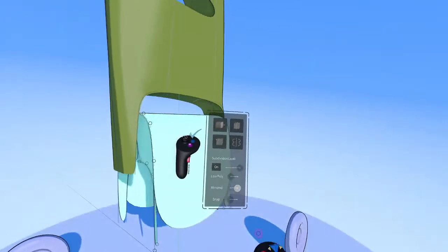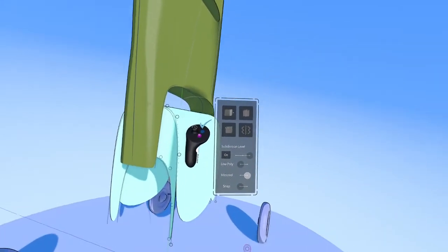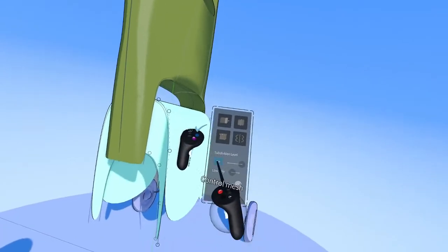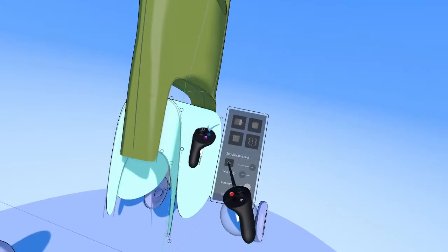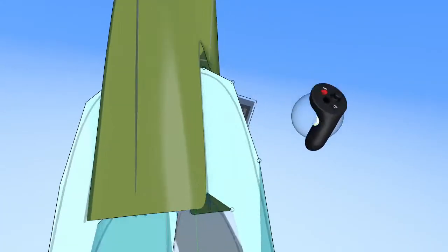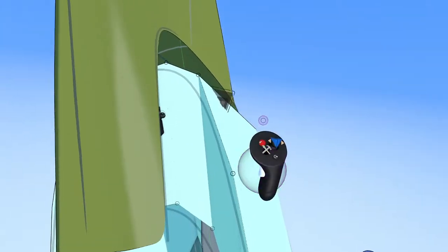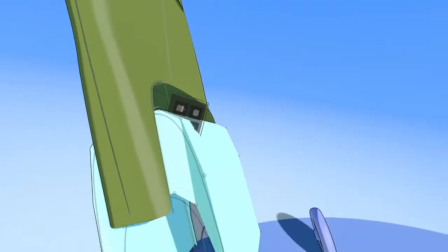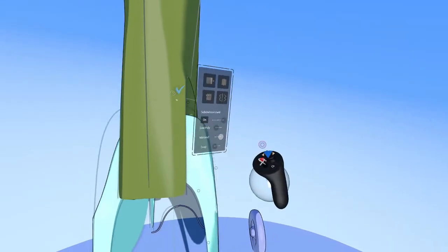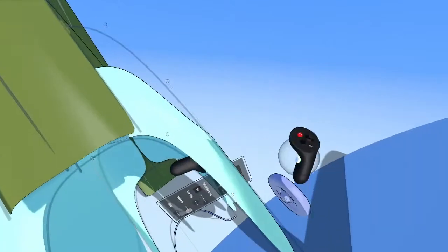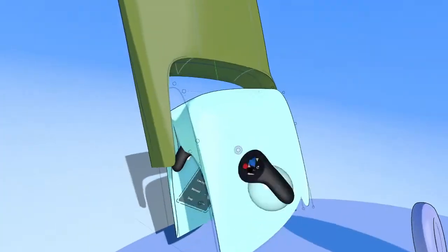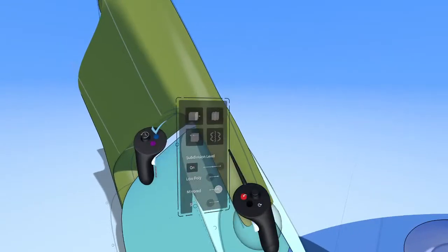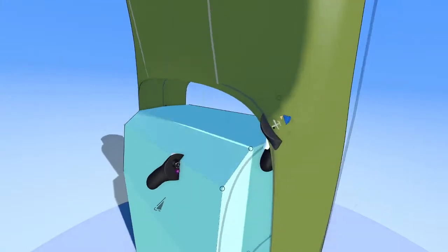Oh, so this is another useful thing that I probably should have been doing this whole time. This is what your sub-D geometry looks like subdivided, obviously, and you can turn that off here with this on-off switch. Sometimes that's helpful so that you can understand exactly how this geometry is flowing. And then, yeah, see, there we go. It was a little tricky for me to see where all those points were following through. And if I just turn off subdivision, it makes it a little easier.